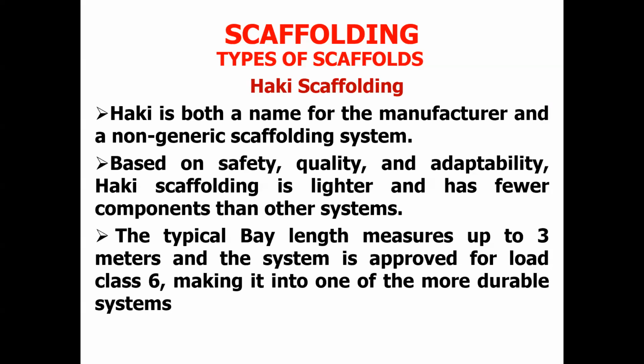When you profile the loads of the people that are going to stand on the scaffold, the tools they're going to use while they are standing there, and also the building elements that will be temporarily supported on that scaffold before they are fixed on the building, you can determine the type of scaffold you're going to use for that particular project.